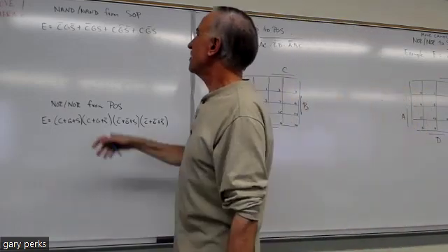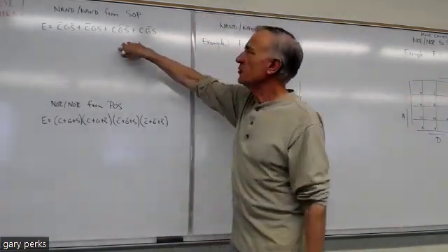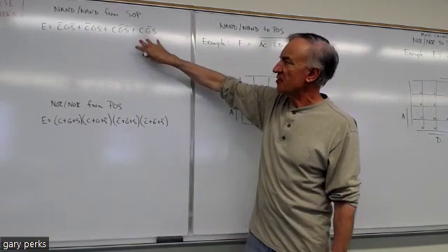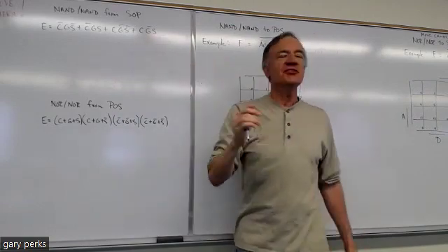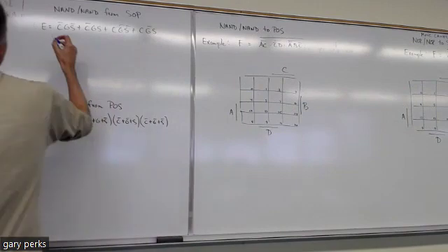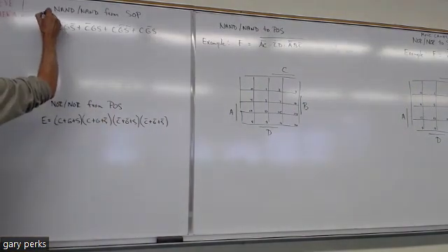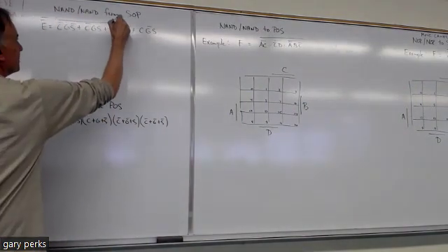All right, so let's start right here. If we want to take this SOP equation and get NAND, NAND, the first thing we're going to do is double NOT both sides. So double NOT here, and then double NOT here.